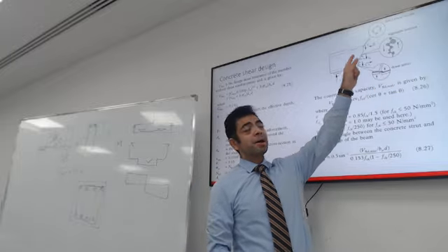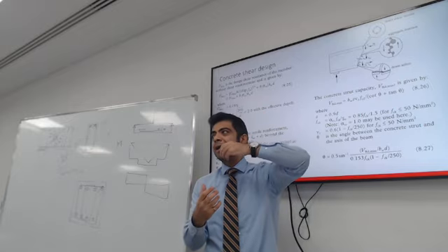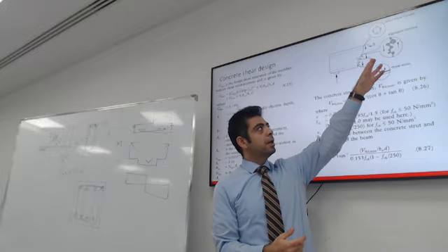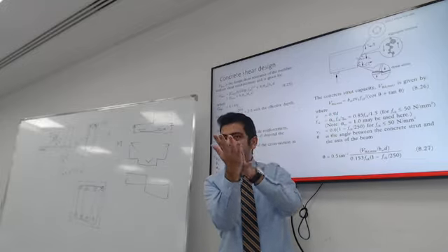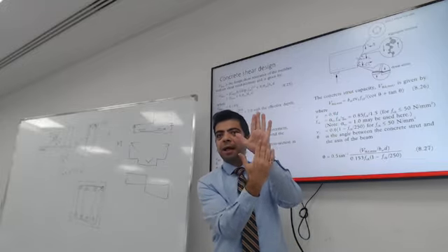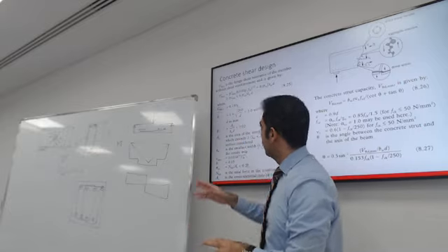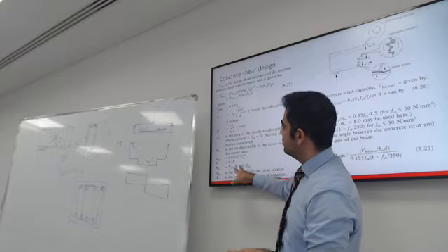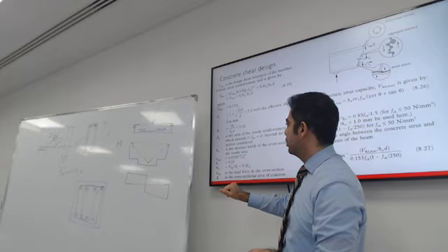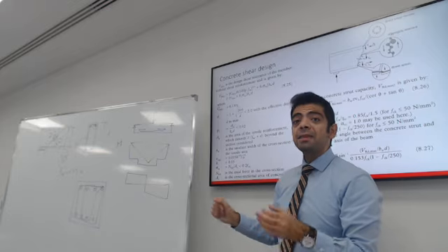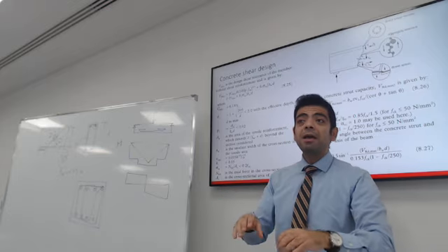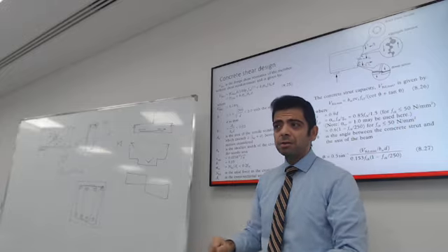And the compressive strength of concrete, fck, which will give us an indication of shear or aggregate interlock and direct shear transfer at the compression block. So when you walk through these symbols, you will figure out that they depend on the concrete strength and the longitudinal bars in the bottom.